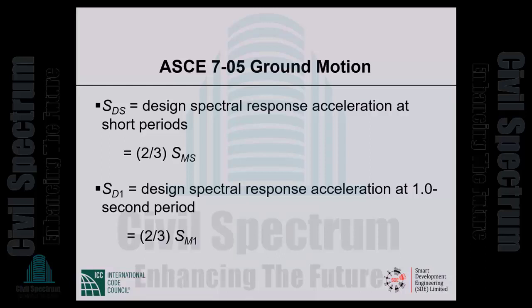What we are saying is that structures designed by the 1973 UBC or subsequent codes are extremely unlikely to collapse on us until earthquake ground motion equals and then exceeds the design earthquake ground motion, which back in the UBC days was 500-year return period ground motion. So 1.5 is the lower bound factor of safety that has been established by analytical studies and observation.